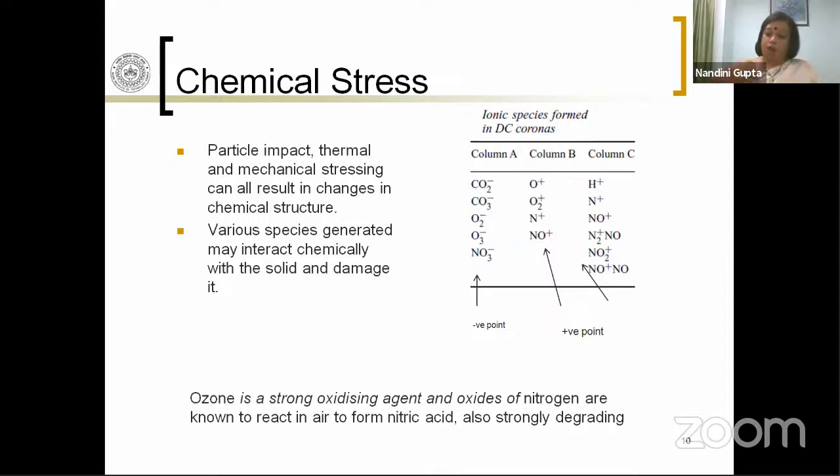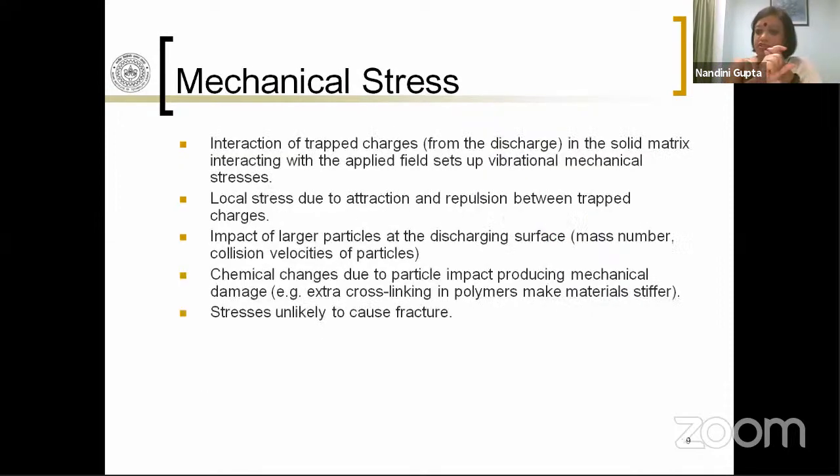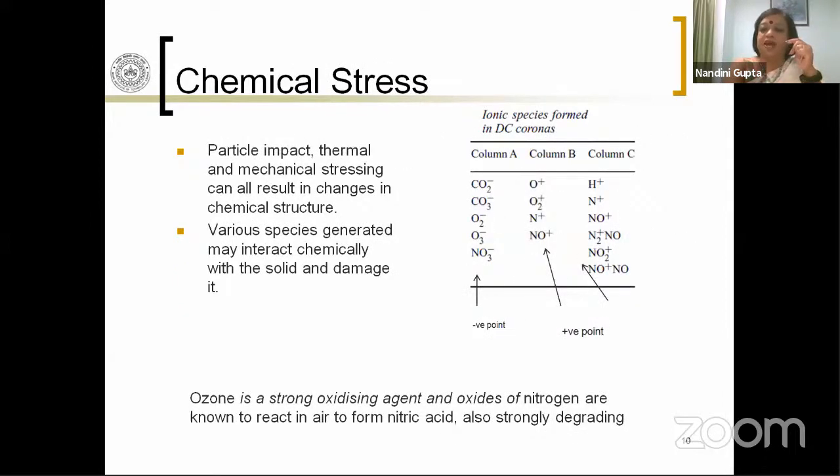So this is what I mean. You have partial discharges happening, and as these partial discharges go on over a long period of time, you have chemical species being generated, you have heat being generated, you have molecular abrasion, you have mechanical erosion. All these processes over a long period of time, and this is very crucial, this is a long-term breakdown process. Partial discharges can continue to happen within the insulation, and over a long period of time, they can result in catastrophic breakdown, in catastrophic failure.